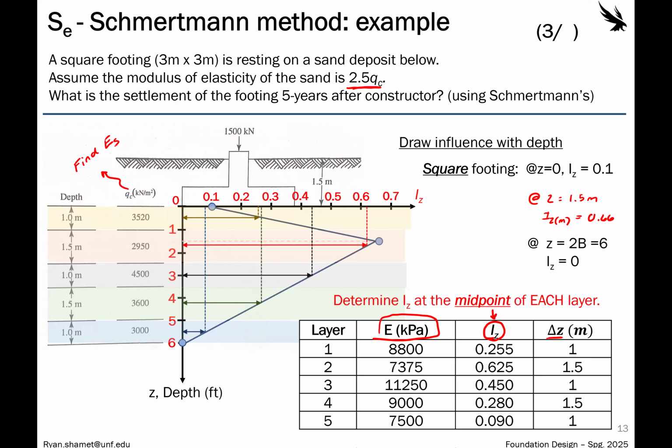So when you're adding these up in our equation, remember, you're only doing this for each one of the layers underneath the footing. We don't care about anything above it, because the depth of the footing is going beneath that. You might have 4 layers or 6 layers above, but we do not include those, because the footing is applying the stress to the soil beneath it.